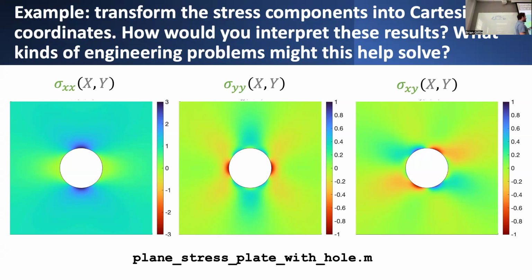And what's interesting is that while the areas on the top and bottom faces of the hole are going to experience larger axial stresses local to the edges, in the case of the Y stress, far away from the hole, the YY stress just goes off to 0. So green being the normalized value of 0. Anywhere you see neutral green, there's 0 vertical stress. But as you get closer and closer to the hole, it's the opposite thing. Rather than becoming a positive tensile value, it's actually compressive.